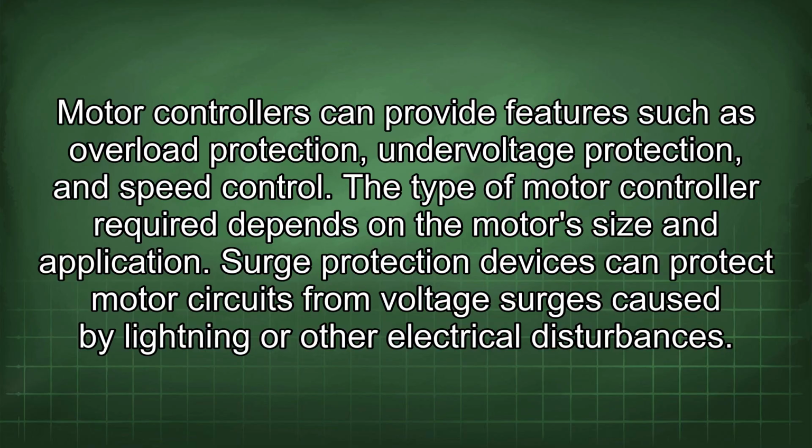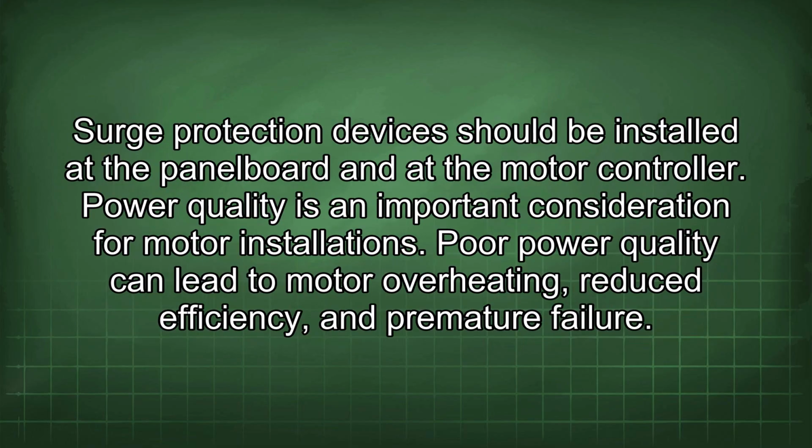Surge protection devices can protect motor circuits from voltage surges caused by lightning or other electrical disturbances. Surge protection devices should be installed at the panel board and at the motor controller.